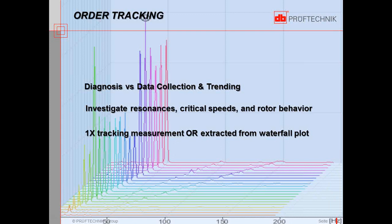Again, a common technique uses a probe, some type of laser tachometer probe or perhaps a proximity probe, looking at a keyway to give you a once per revolution event. This signal is then used to track the amplitude of the vibration at the 1x. Because the tach signal is by definition synchronized with the 1x vibration, in addition to the amplitude, we also derive phase data.